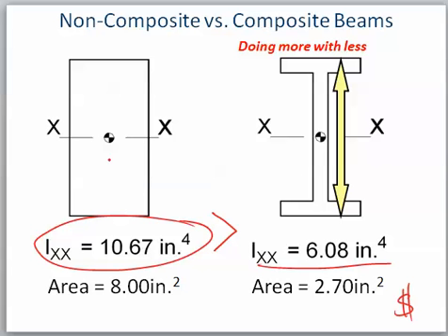If they give you a solid block of steel, the area becomes 8 inches squared, which means there's a lot of steel there. But over here, if they give an I-beam, I want you to notice what happens to the area. They get almost 3 times, probably closer to 2 times. Let's change that to a 2. They get over 2 times the moment of inertia using an I-beam. Over here, do they get 2 times for every bit of area they have? No, they don't.